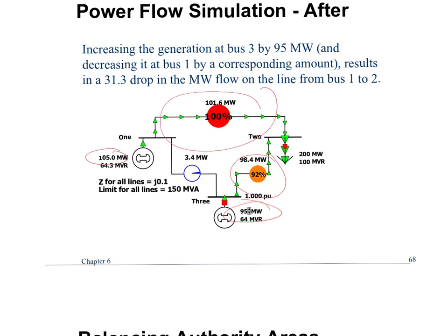So if I was to look at this system design, this is a poorly designed system, right? Because this system only has one line that is so lightly loaded, 3.5 megawatts. Forget it. This is a really poor design. So I wouldn't even put that line over there. What I would probably do is I would run a parallel line into that location. And parallel lines are not that uncommon.